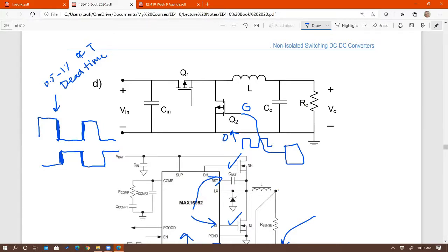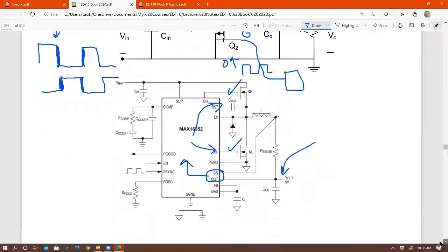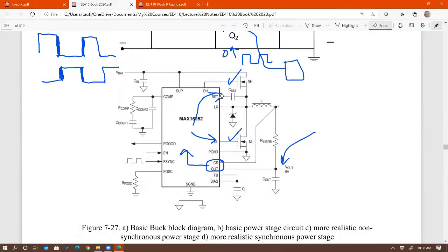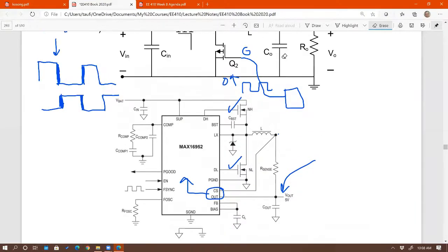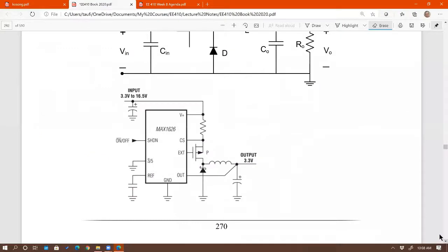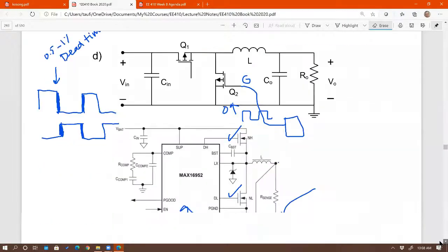So you can't have just one signal with an inverter. You have to have two, right? Because these are both MOSFETs. I was saying you can't have one control circuit going into Q2 and then an inverter tied to Q1 with that same input signal, because you need a little bit of a delay. That's correct. Which one has the bigger or smaller duty cycle will be a function of output and input, as you will see, because the top one could be a smaller duty cycle than the bottom one, right?